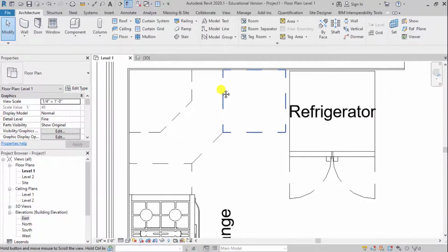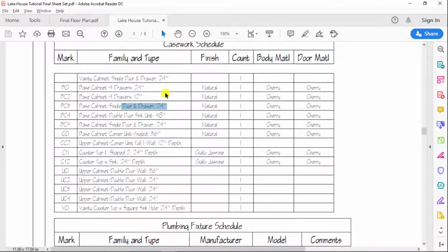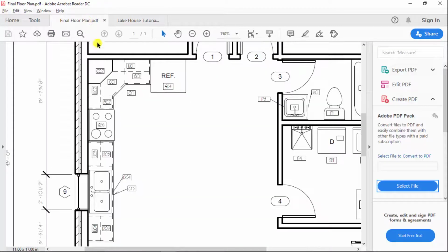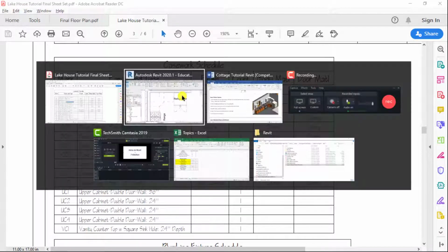So then the last thing for our wall cabinets is going to be to continue to put them in, whoops, wrong page. So I need upper cabinet 1, which is going to be longer because it's going to go from this, which is narrower, all the way over to the edge. So UC1 is going to be a 3-foot double door wall.